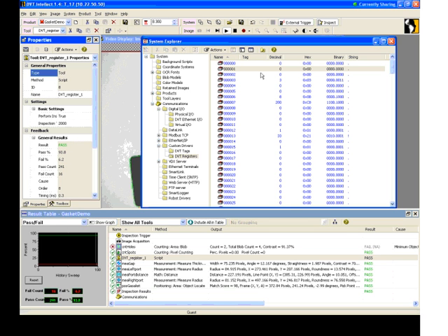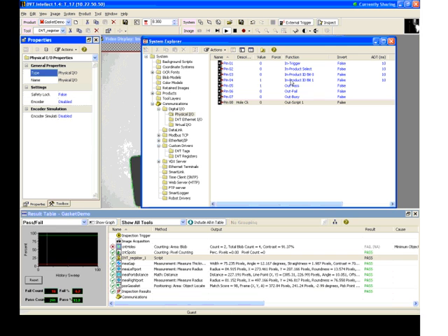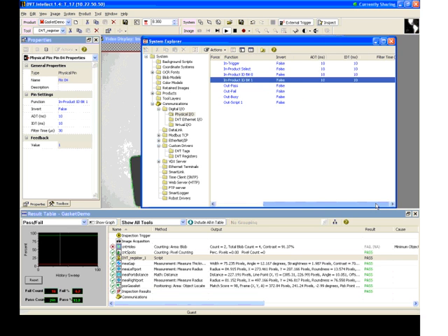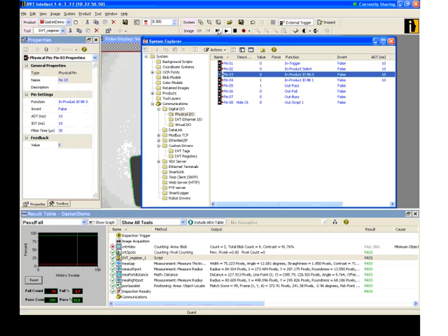So that about covers it for the communications with digital I/O. Under this digital I/O function here, we have the physical I/O, which is where we can work and configure these functions right here. There are some other functions to realize with this. We have some bounce times and some filter times in here. But the main function I want to make sure we are covered with are the different functions that we can configure each one of the pins, and to make sure that we have the inspect button on. Otherwise, these will not update for us.